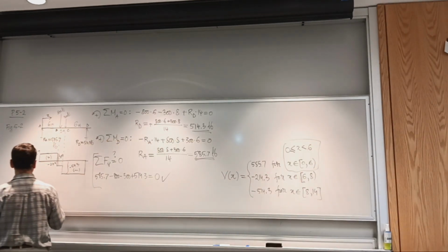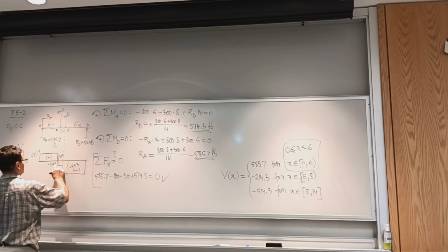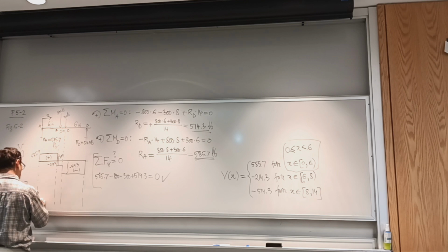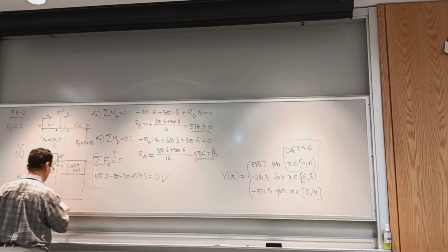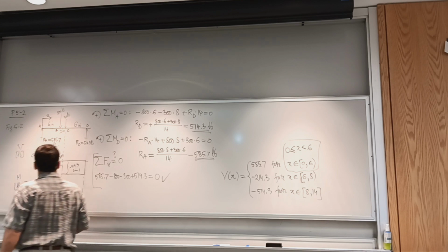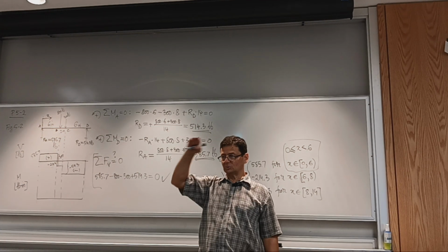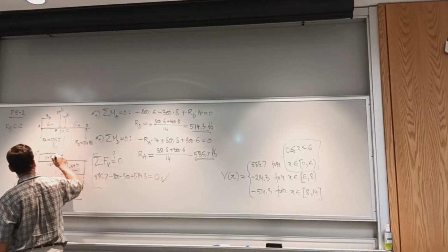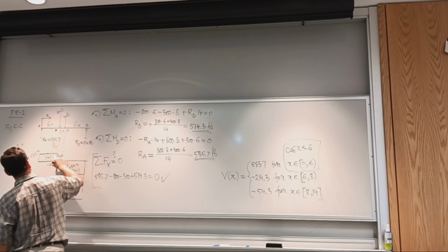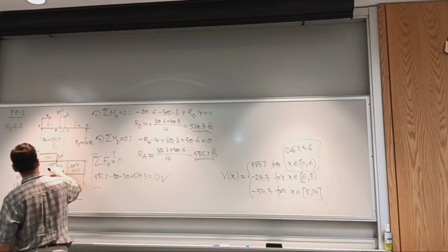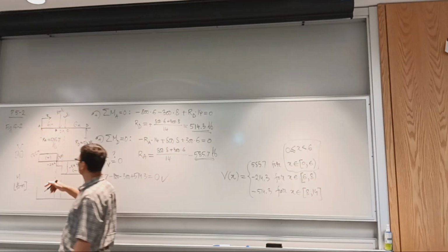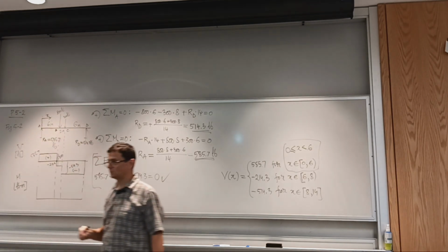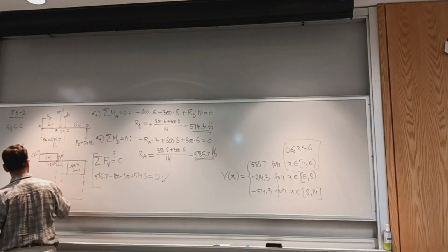Okay, let's take care of the moment diagram now. Here clearly we know the beam is smiling throughout, and that the moment diagram is always going to be above the x-axis. It will remain above the x-axis. What else we anticipate? We know there will be straight lines, changing slopes. So it starts with a positive slope, and then it reaches a maximum because the shear diagram goes to 0. There's a change in slope, firstly less severe, but this is negative slope and going to a bigger negative slope.